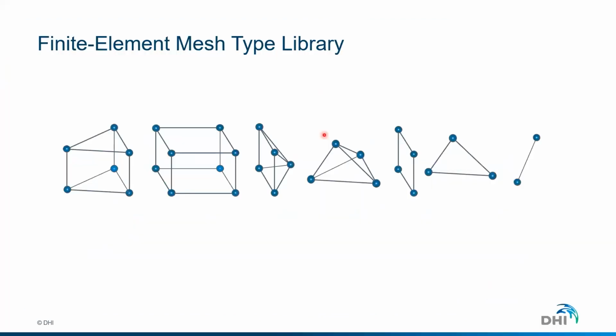3D meshing, in simple words, means that we have extended the library of finite element methods, and this is something not done recently. Since version 7.0, we have the possibility to introduce 3D unstructured elements. Unstructured elements in 3D will be tetrahedra, prisms, hexahedra, and others. So we basically extend the library, which gives us the flexibility to introduce new types of elements and therefore accommodate to complex geometries.